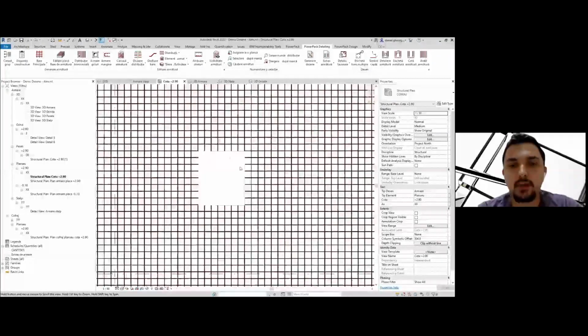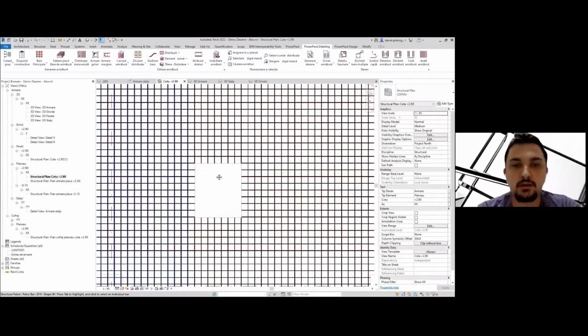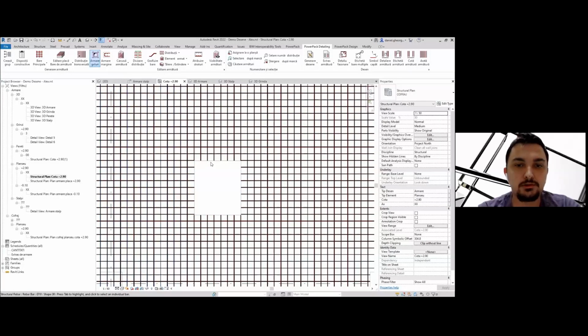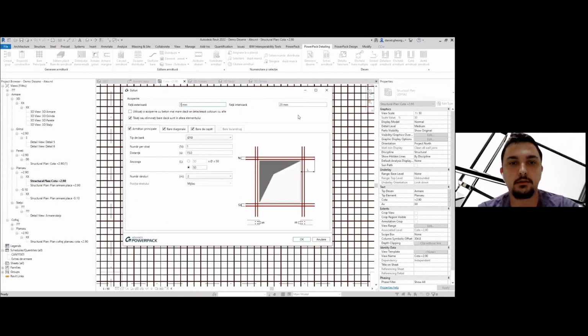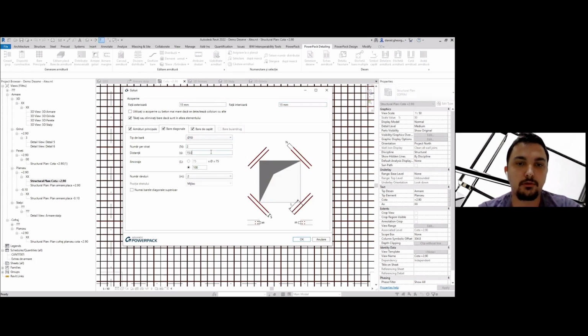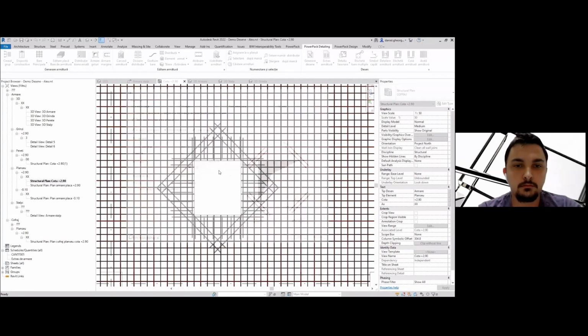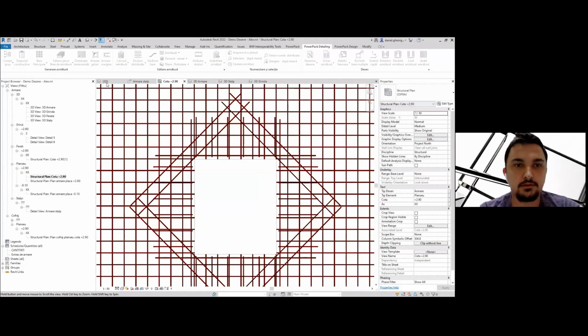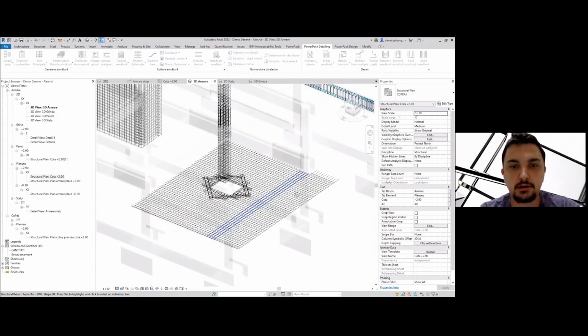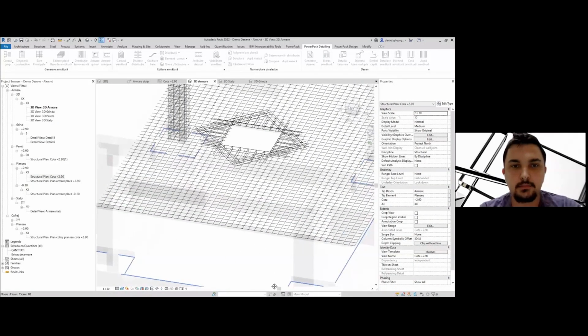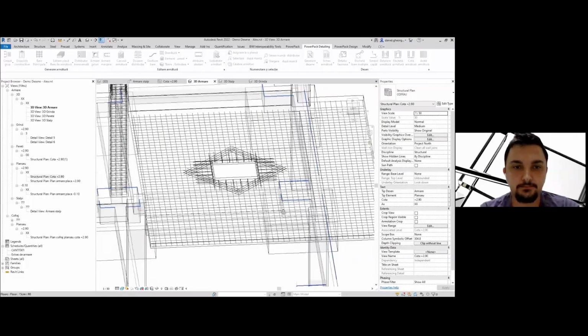And not only that I'm able to automatically split the rebars around the opening, but I'm also able to generate an opening rebar cage also from a parametrical point of view. Okay, everything looks just fine. Yeah, I have a 3D rebar cage in a matter of seconds.